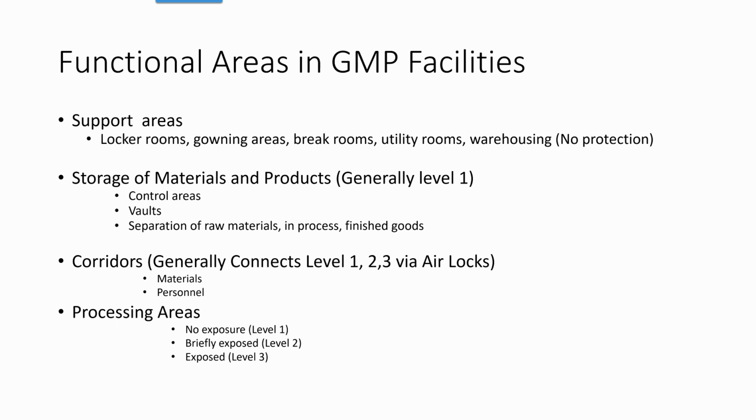If the unit does not have contamination risk, it can be placed outdoors. You can do that, no problem at all. The only thing is that when you bring it back indoors through a pipe or whatever, it has to be caulked so that you don't have bugs or rodents getting through there. Like a 1/4 inch. If you can see light through it, they can get through it. It's crazy, those little mice.